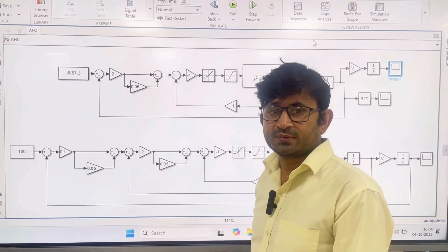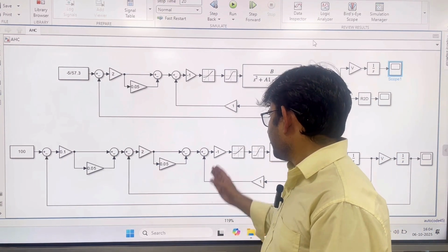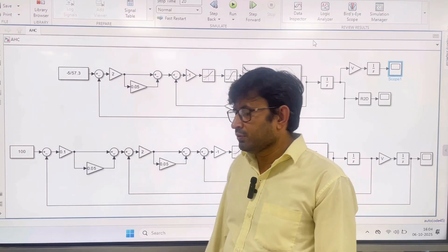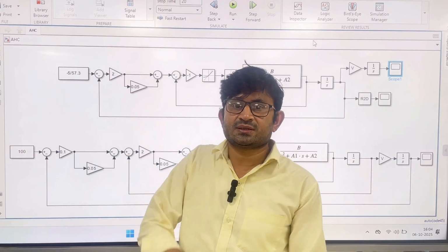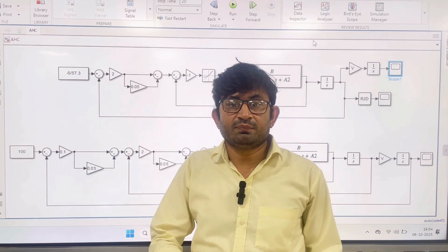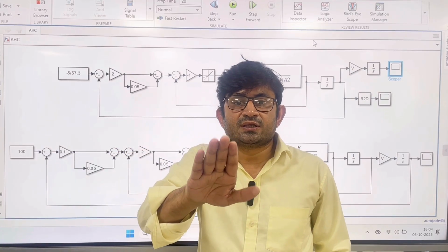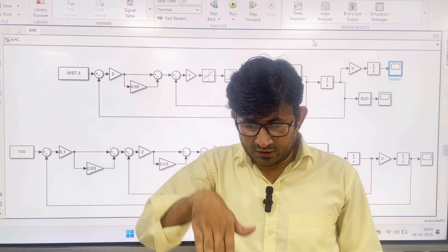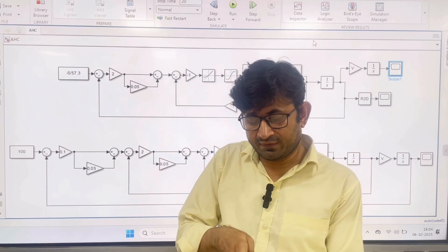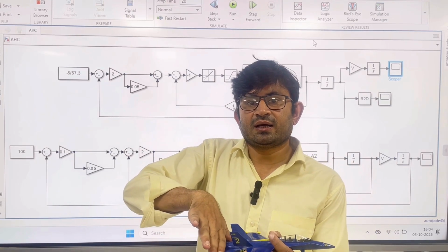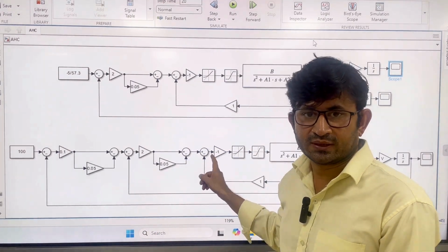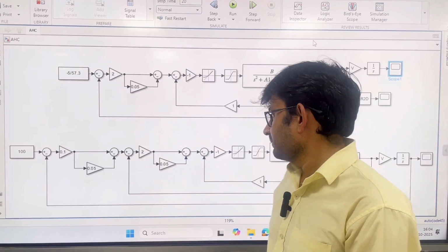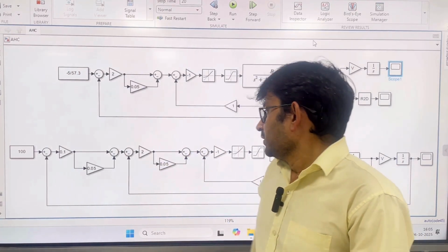You may put actuator dynamics also in first order. I have also explained the minus sign. I do not want my gain to be negative, that is why I put the minus sign. Why? Because elevator up is considered negative, but pitch up moment is considered positive. By deflecting the elevator upward, which is negative, you get the positive moment. That is why I multiplied by minus 1 here. I do not want my gain to be negative. So one thing is clear, right?